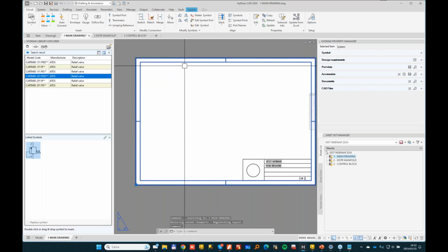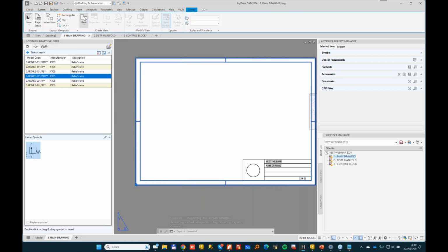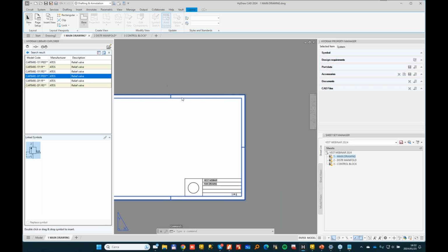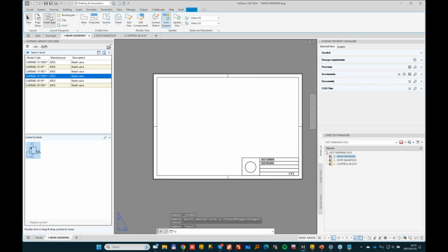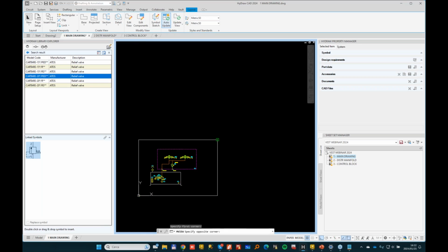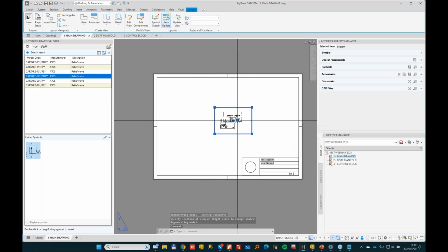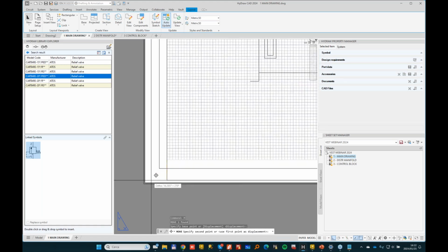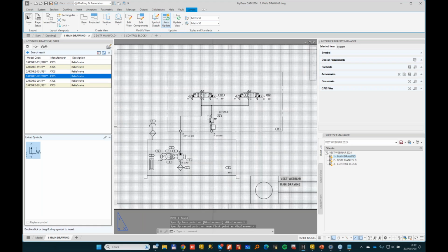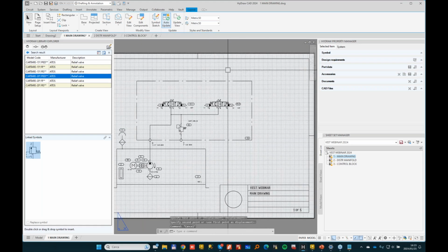It is not. So let me add a layout. I thought it was there, but let me just from the model space. I think when I built the block, I included also the layout. Let me insert the view, which is exactly this one. Enter. And this one, I want to keep it 1 by 1. And let me move it here to the 0, 0 location. Yes, so this is the layout displaying the drawing inside.